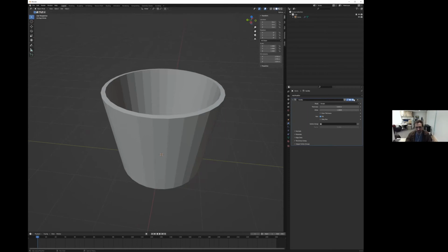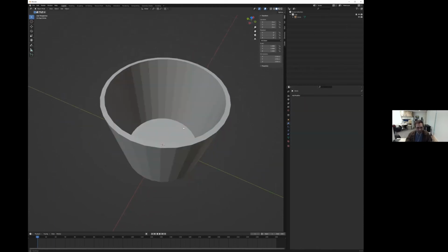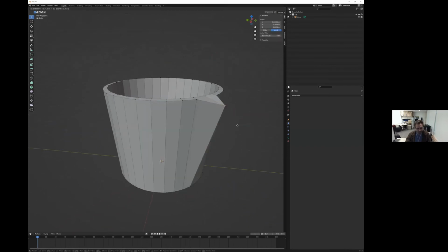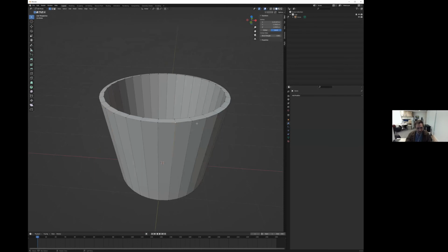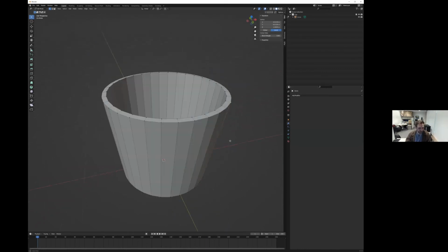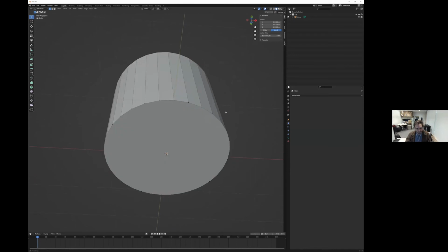And so what we can do here is apply it by going down here and pressing this arrow and then hitting apply. All right, so now we can edit this side because now it's taking into account that you have applied the geometry modification. We are now essentially adding that to the mesh and giving you the vertices in the proper ways of being able to manipulate it.